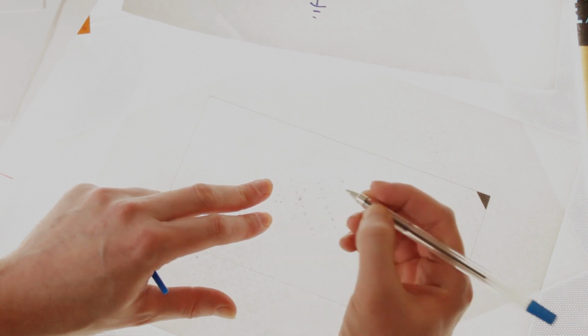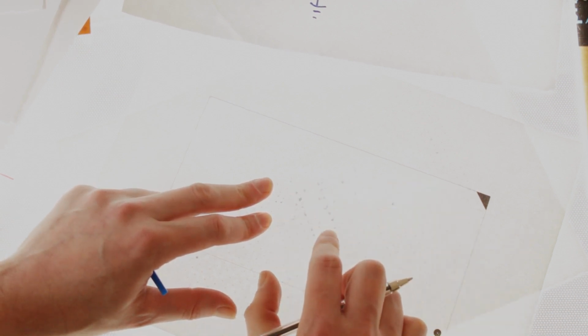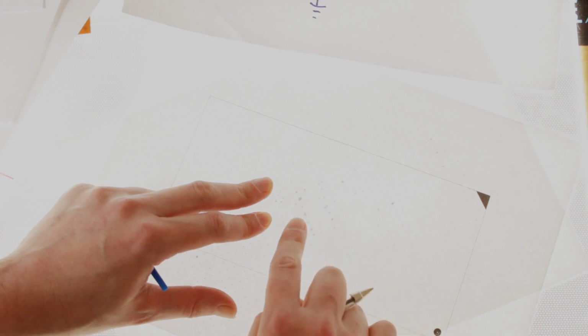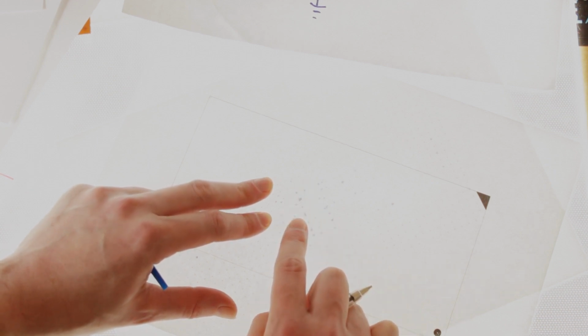So let's just, I will mark out where the pins are gonna go. And I'm not actually really bothered about drawing the pads or drawing the pins properly on these templates, because I will just import a pad into KiCad, so I can overlay that exactly where it's supposed to go, so that at least the holes will be drilled properly, and I should be able to mount all my components in as they are supposed to go.